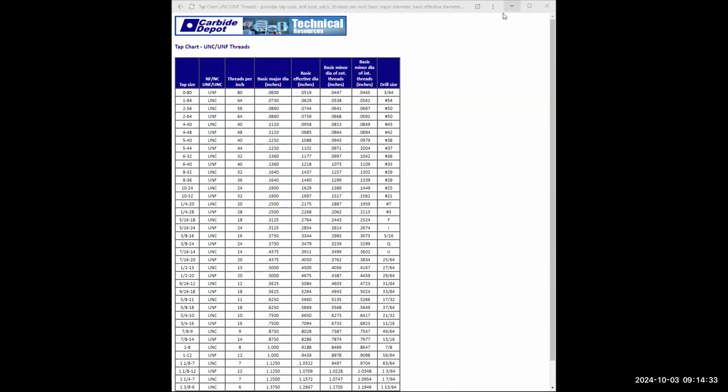Click, enter, and this is going to be percent C space 0.38 space, and then type out the word THRU, enter, enter again. That means it's a 3/8 diameter hole that goes all the way through. That is how you spell it too. It's not misspelled. That is the abbreviation for the word through, because the hole goes all the way through the part.